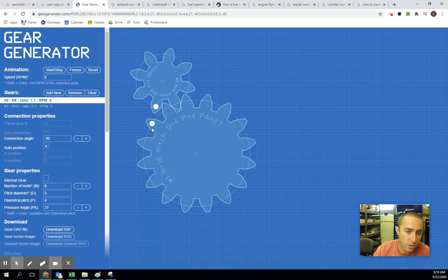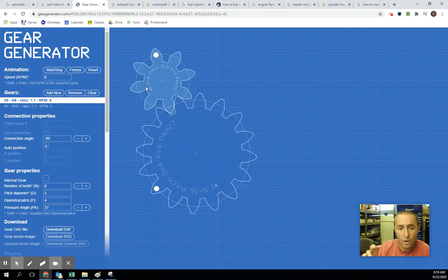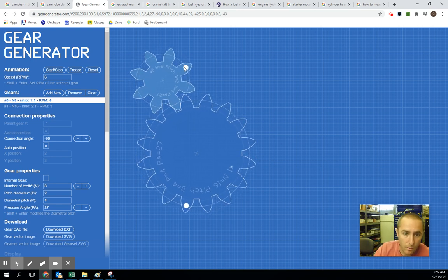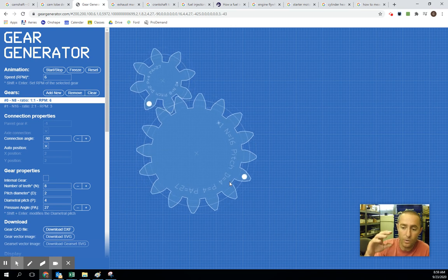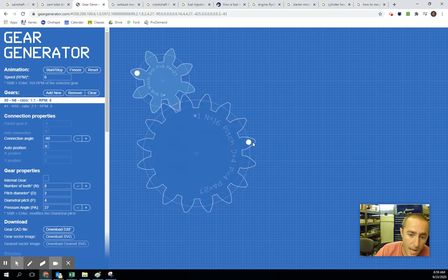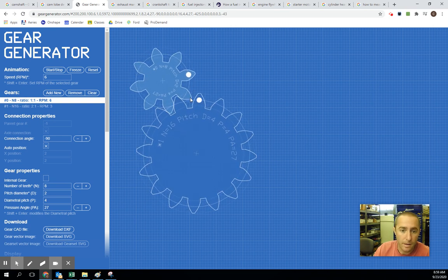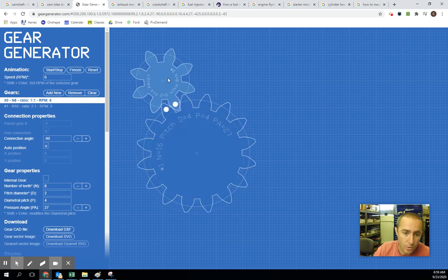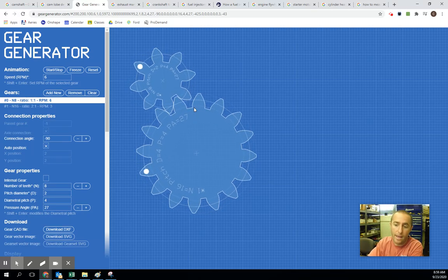When you install two gears together in a vehicle, you actually have to install them at the right tooth to tooth contact to make sure that everything's opening and closing at the right time. And so you'll have these timing marks that help with that. But the main emphasis is you have a 2-to-1 ratio between camshaft to crankshaft, and that affects the timing.